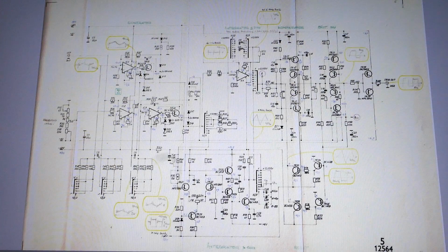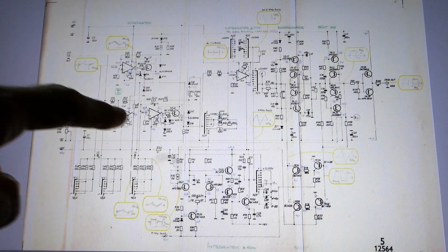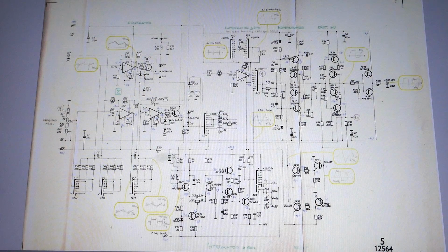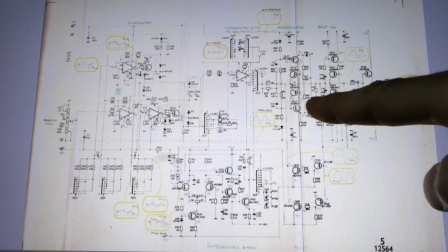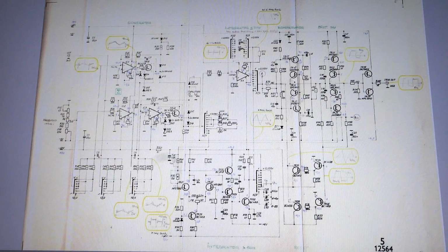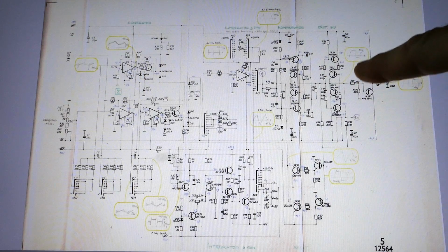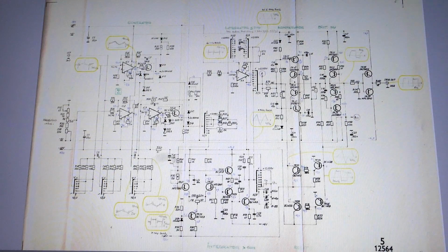And here is the first part of the main schematic, and I found it on some German website. Somebody was drawing into it. Here is the fine frequency potentiometer, the 3 op-amps, then some integrator producing a triangle wave, and this circuitry turns it into a square wave. And the square wave also goes to the trigger output. And the triangle wave goes to point A and the square wave to point B, which continue to the second part of the main schematic.